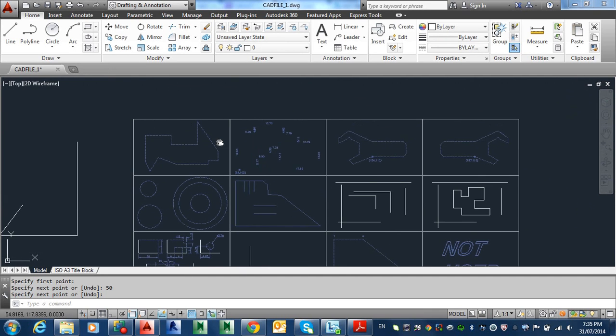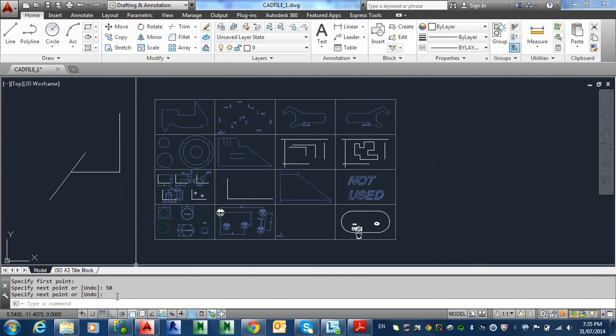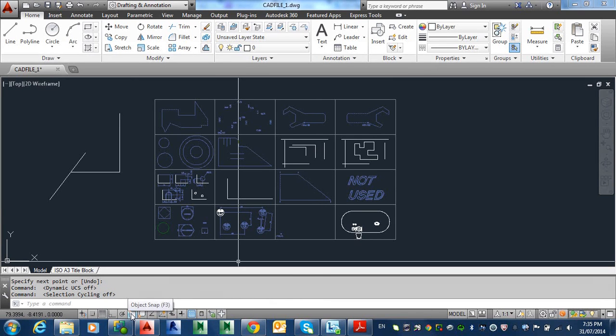All right, so here we are with my actual drawing. We've got my command line down here. Now, generally, what the book says is you turn everything off when you first start your exercise, and I agree with it in the main. It does also say to turn off the object snap. Initially there's a couple of exercises where we don't need the object snap, which, as we'll read later, is a way of latching on or hooking up to endpoints, midpoints, intersections of line work. The book says you can use it, but then turn it off when you don't need it.